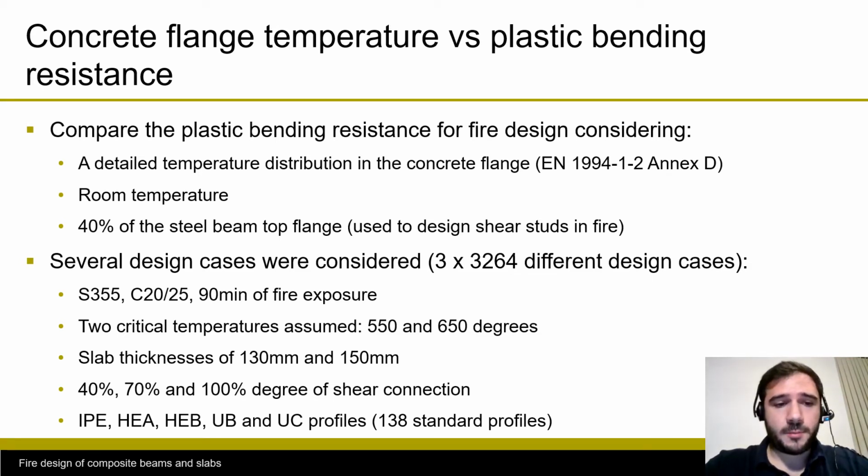For these three options, several design cases were considered, more than 3,000 cases, which considered S355 steel, C20/25 as concrete grade, 90 minutes of fire exposure, 2 different critical temperatures, 2 different slab thicknesses, which cover the typical slabs in the market, 3 different degrees of shear connection, and 138 standard steel profiles.